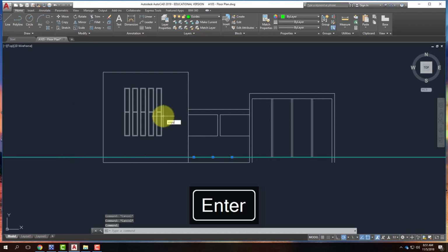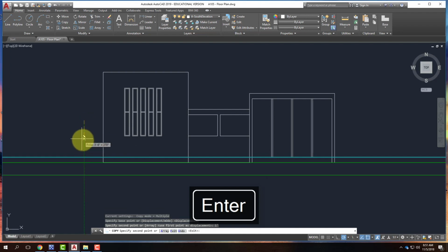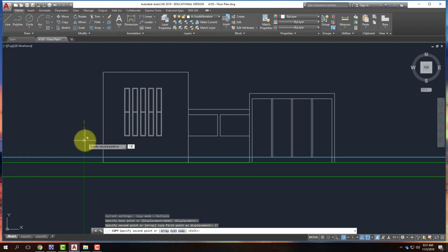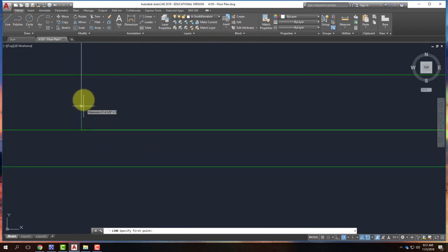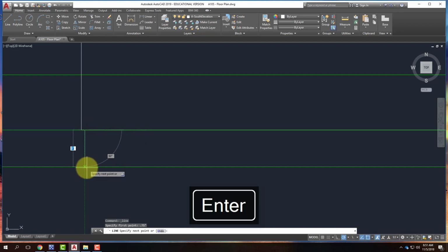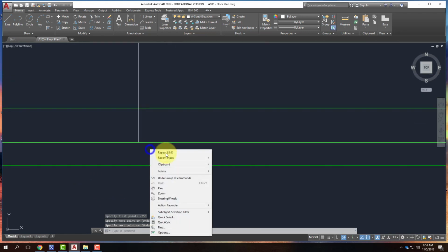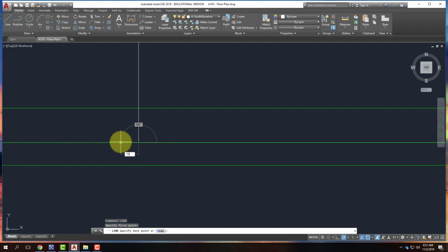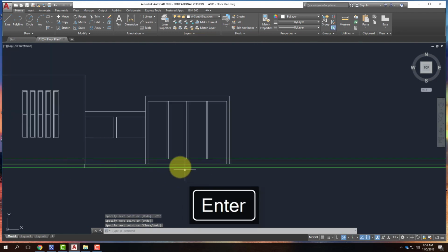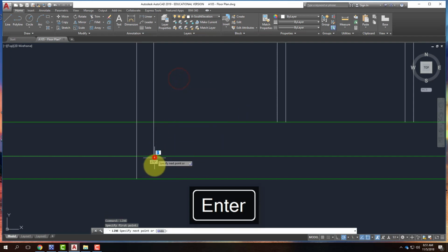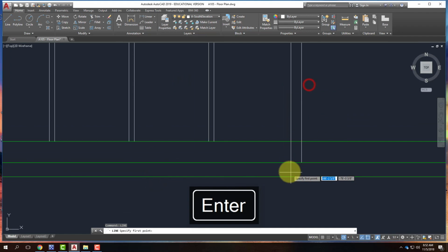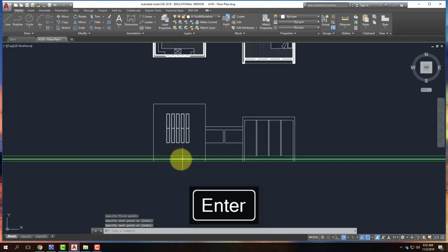Let me copy this. I'm going to go down a foot for the bottom of the building, and then I'm going to go down another 8 inches to represent where the ground would be. That's the ground. Typically, there's a little bit of a reveal between the edge of the building and the foundation, so I might come over by a 1/2 inch or 3/4 of an inch before I draw the foundation of my building. These ones here would just keep going all the way to the ground. Like that.